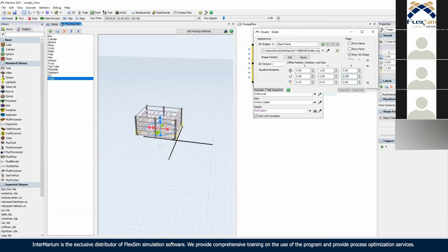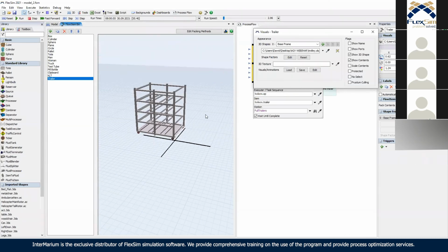This will mean that it's a little bit higher. Still not enough, but FlexSim calculates that the size of this object is this yellow outline. So the 1.24, 0.15, but the graphics will be a little bit bigger. I think it should be like 0.13 or 12 here to be the correct size.